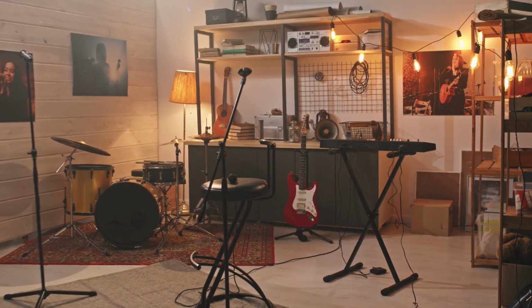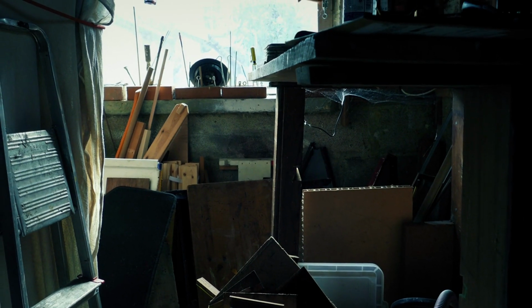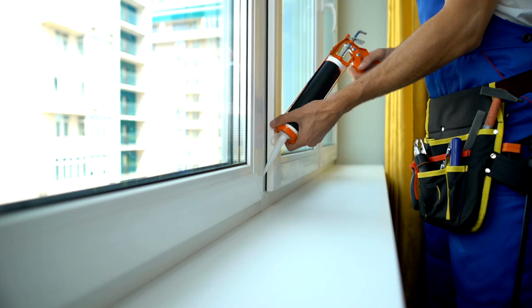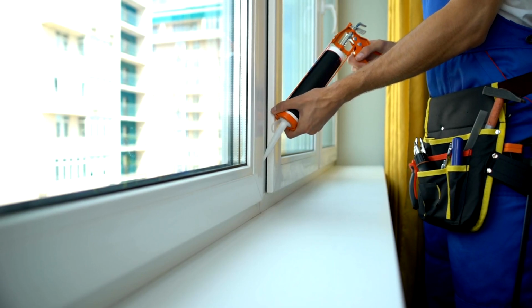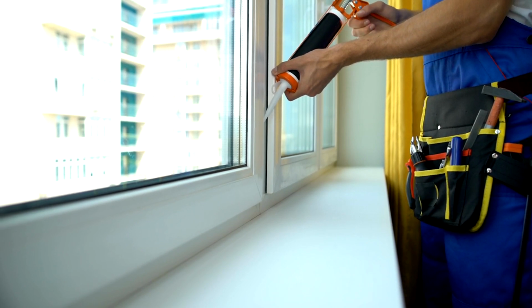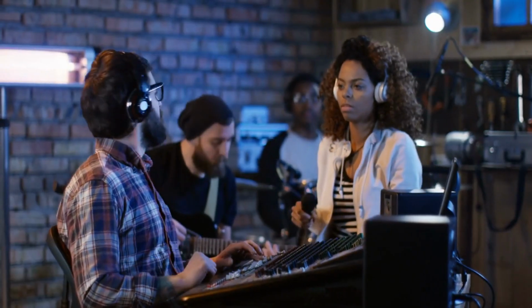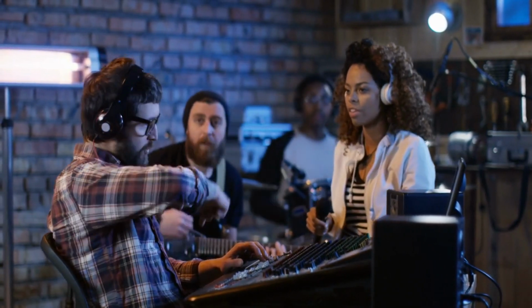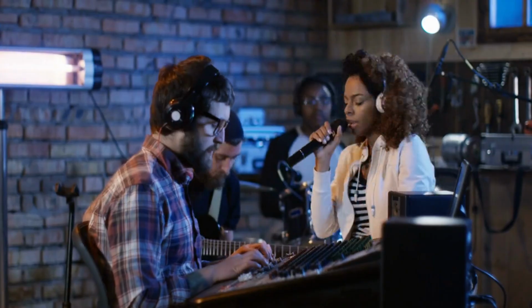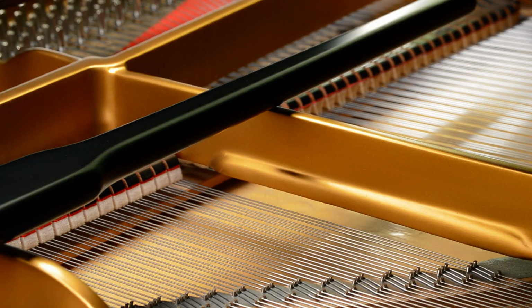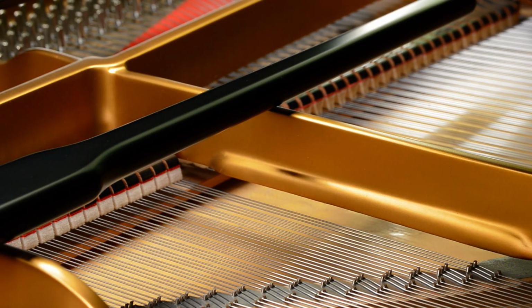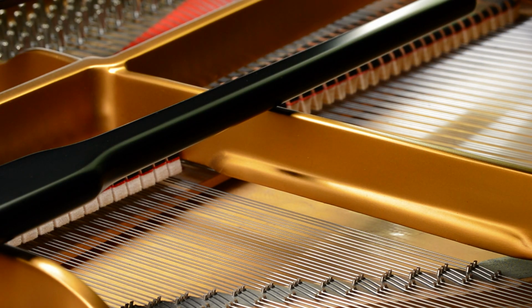Adapting a garage for studio use. Garages present unique challenges due to their typically larger size and hard, reflective surfaces. Soundproofing may involve adding insulation to garage doors, sealing any gaps, and installing additional layers of drywall. Acoustic treatment should focus on controlling reflections with panels, treating the floor with a thick rug or carpet, and adding bass traps to the corners. The higher ceilings in garages can be both a challenge and an opportunity, requiring additional treatment, but also offering the potential for a more spacious sound.